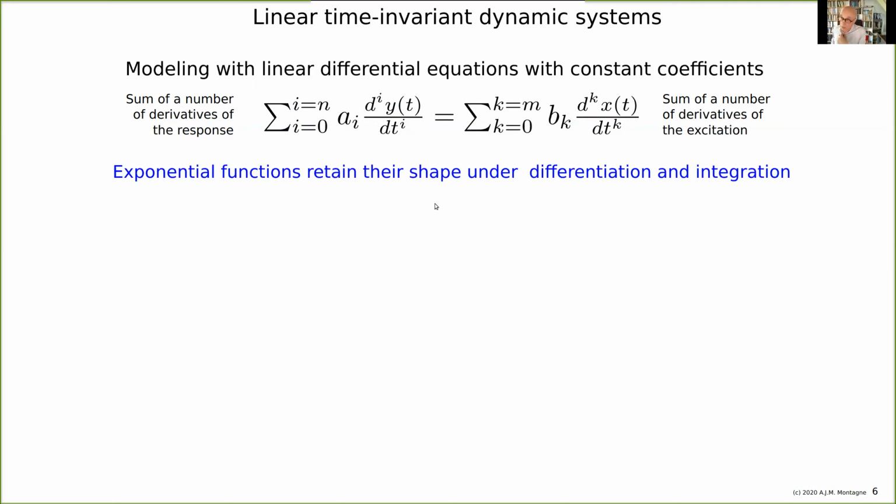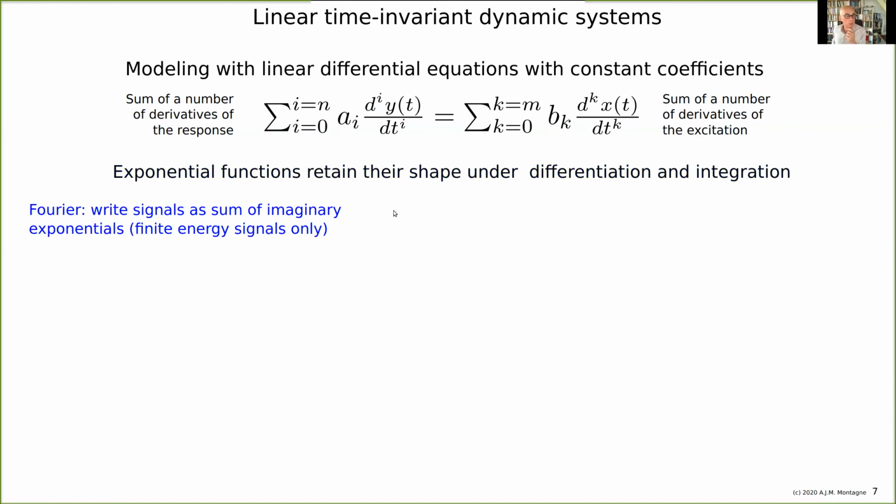And that's why you have your sine wave generator on your lab table, because if you want to know something about the deviation from linearity, you can say, well, a sine wave is in and there is no sine wave out. Then it must be nonlinear, because if it's a linear system, you put a sine wave in it, there will be a sine wave out, and they will have a different amplitude and a different phase, but that's the only thing. That is the property of linear dynamic systems.